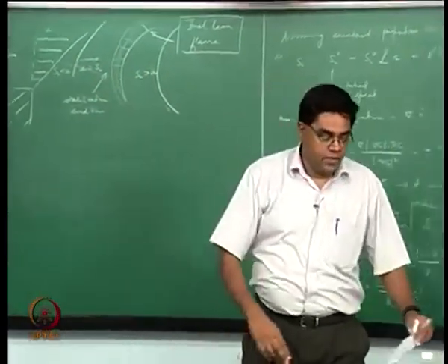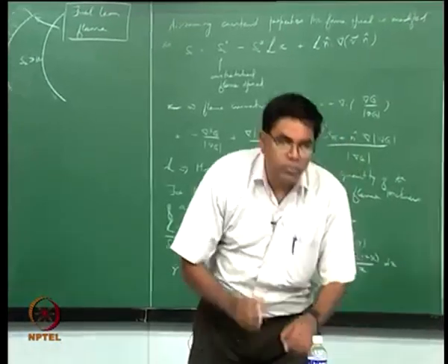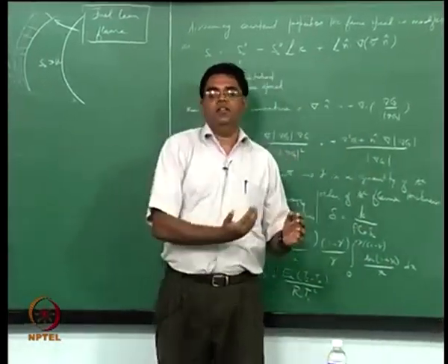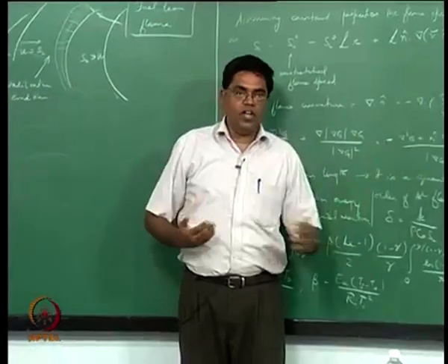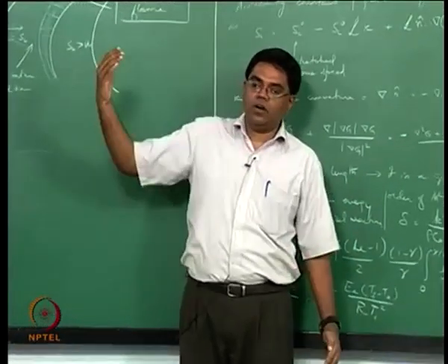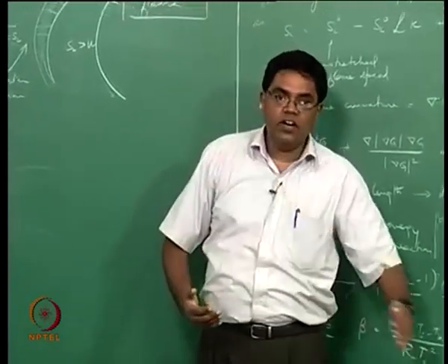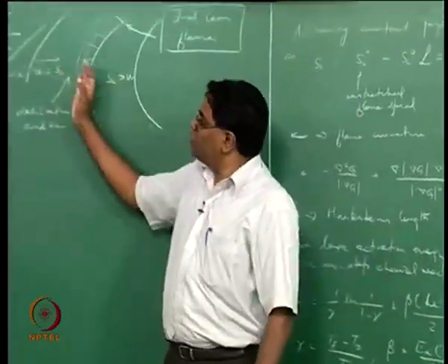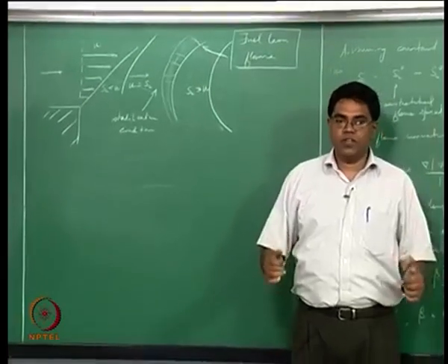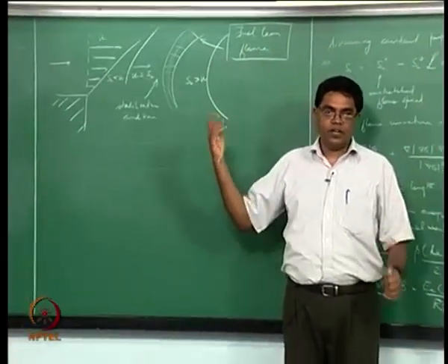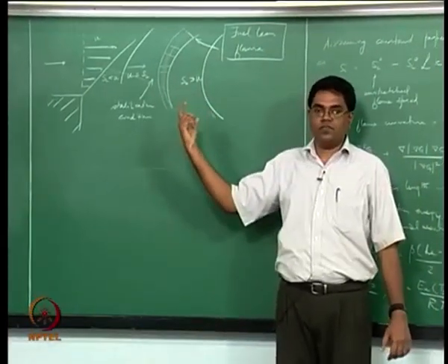So effectively it now becomes a local match between a varying flame speed and a varying velocity. The flame speed is not uniformly varying, the velocity is linearly varying, and this match is what is going to dictate how the flame is stabilized locally there, and therefore correspondingly a flame standoff distance.